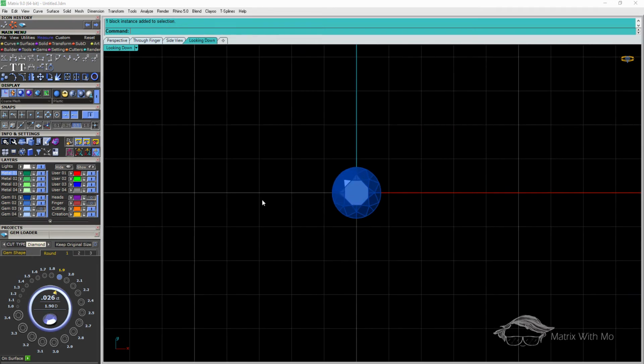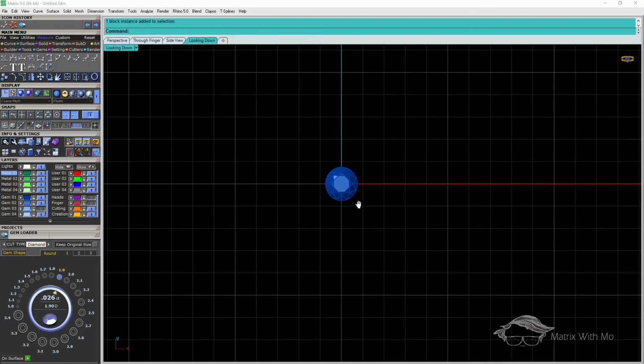And so now we can set up our marquise shape. We know our length, so I'm going to draw a line with single line from both sides. And we'll go F4, 2.5 on each side. So enter there, hold shift, click, and I'll make that red for now.